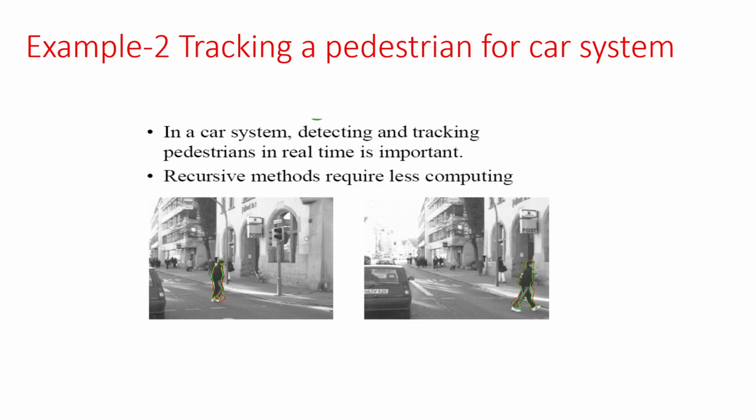So, here you are first detecting the object, and you are creating the object, or a radar can also be used. You are detecting the object and deriving its trajectory. This person is crossing, so it is a crossing target. The system will identify that it is not inside my ego lane, nearby my ego lane, where ego lane means my driving path, so that I do not need to apply my brake and all. So, this is the tracking.